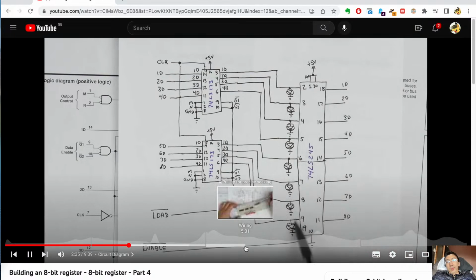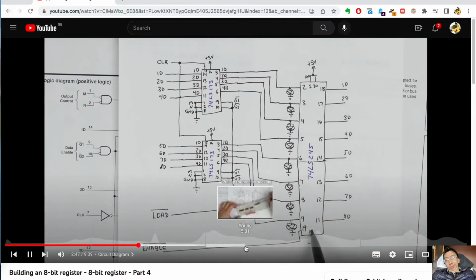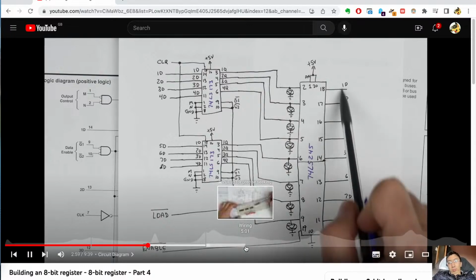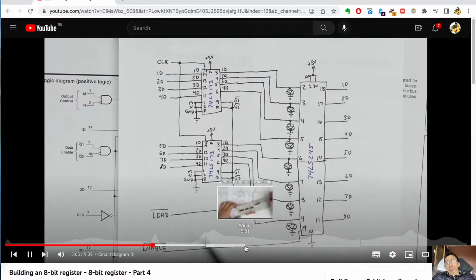You can ignore this line, I needed to draw this bigger than I thought. And then we're using the 74LS245 to actually control whether it goes back out on the bus or not. There's an enable line that the 74LS245 has, and it's an inverted logic line, so it would normally be high, and then you bring it low to enable it. When you bring that low, then whatever this is will actually get output. But if the enable is high, meaning it's not enabled, then this is simply shut off, and it's not outputting a 0 or a 1 to the bus.